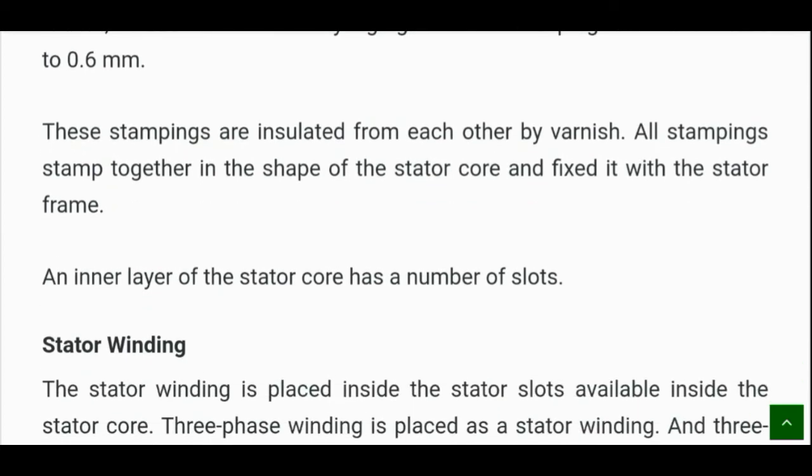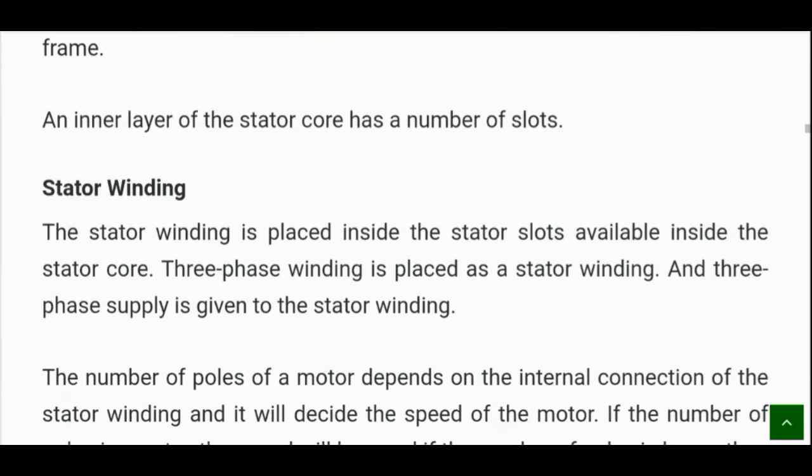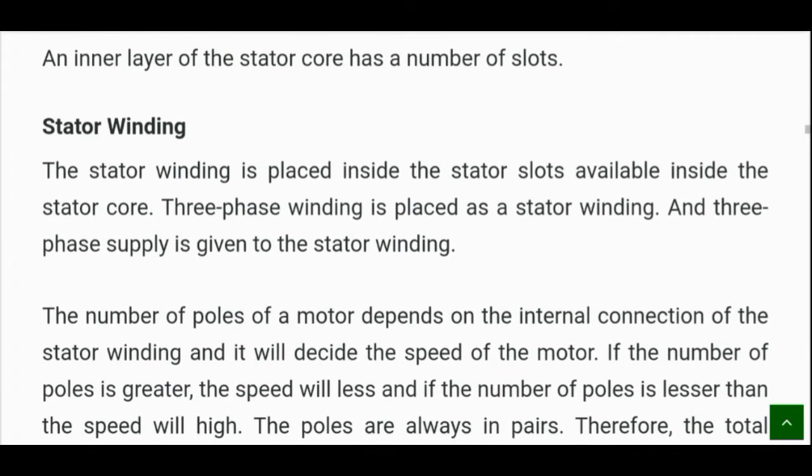These stampings are insulated from each other by varnish. All stampings are stacked together in the shape of the stator core and fixed to the stator frame. The inner layer of the stator core has a number of slots.